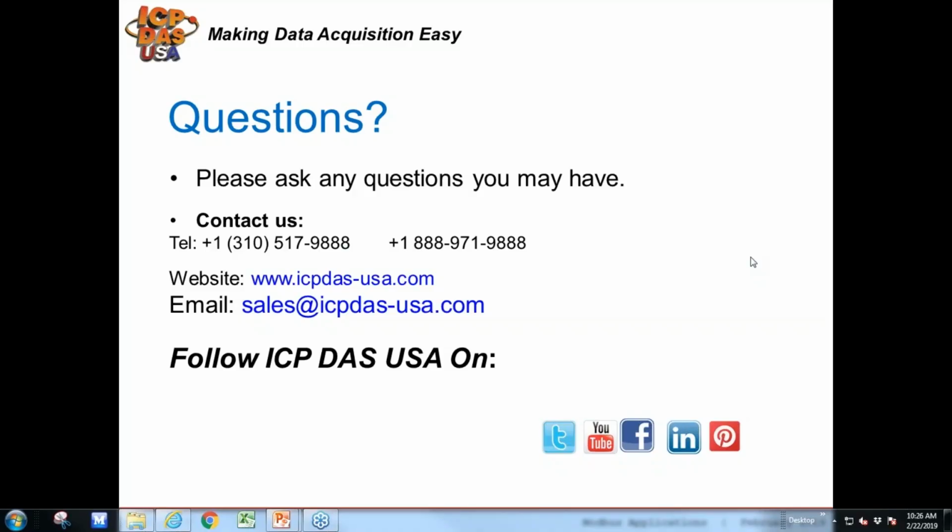The next question: can you use the same slave address on two devices, but with each connected to COM1 and COM2? We have a feature in our TGW which allows for virtual IDs. So with that feature, yes, you can. But traditionally, each address must be unique along a single bus.